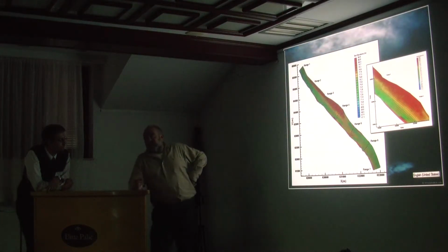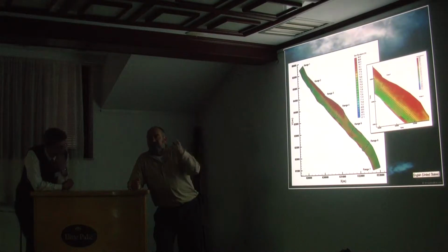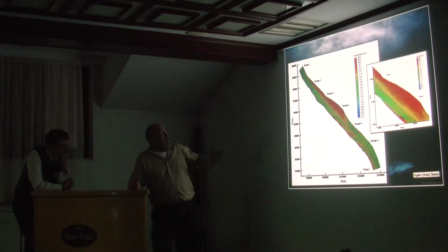For 2D and 3D models, there is first a general overall calibration, which includes checking discharges and free surface elevations. From the 2D model, we have the unit discharges. We can integrate the model results, the unit discharges, to obtain the total discharge for a cross section, and we can compare it to measurements. Then we can also compare free surface elevations.